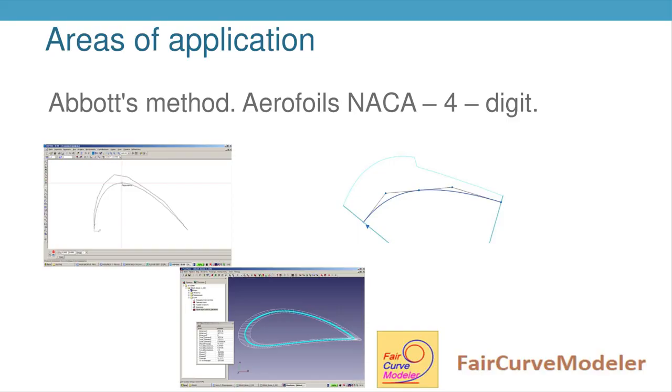An obvious direction for improving the method is to construct a reference profile in the form of B-spline curve based on measured data with the smoothing option and construct a middle line at the form of an F-curve. In this case, in order to accurately fix the position of the point of greatest profile thickening on the midline, it is necessary to use the option of fixing tangents.